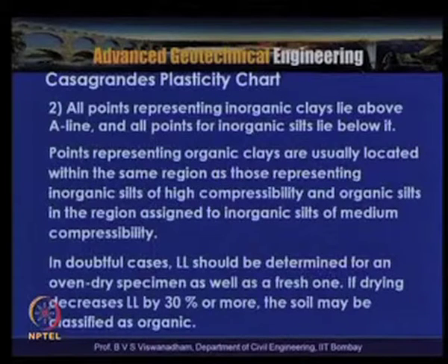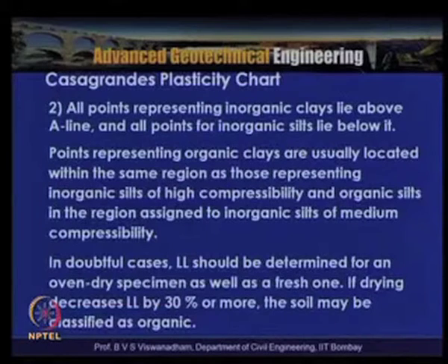All points representing inorganic clays lie above the A line, and all points for inorganic silts lie below the A line. Points representing organic clays are usually located within the same region as those representing inorganic silts of high compressibility, and organic silts in the region assigned to inorganic silts of medium compressibility. In doubtful cases, the liquid limit should be determined for an oven-dry specimen as well as the fresh one. If the decrease in liquid limit is say 30% or more, then the soil is classified as organic because of the loss on ignition of the organic matter.